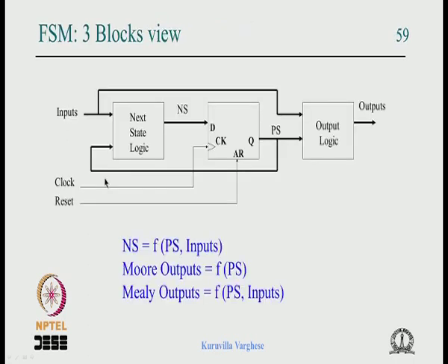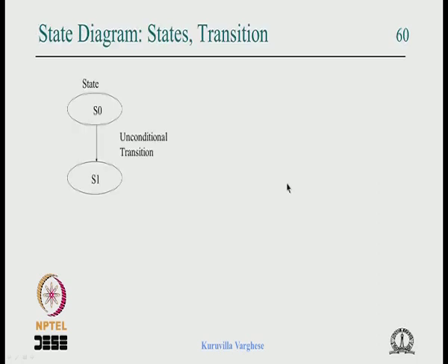The present state was 0 0 0 and we decode it to produce some output. A clock comes, irrespective of the input, the present state is decoded to the next state 0 0 1, and when the next clock comes, that is loaded there. The controller is in one state, and upon the clock it transits to the next state. There is no input condition.